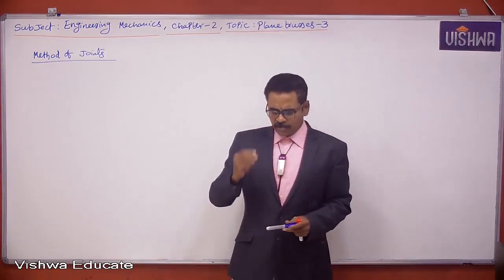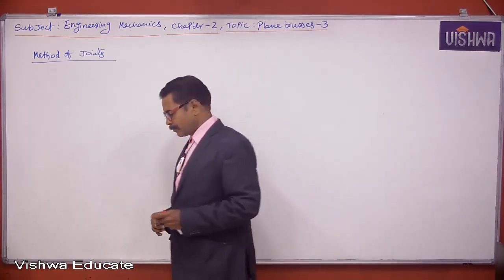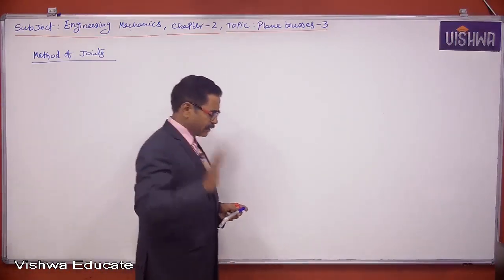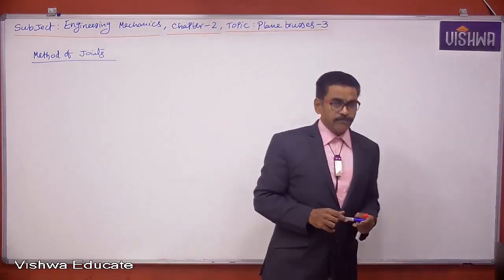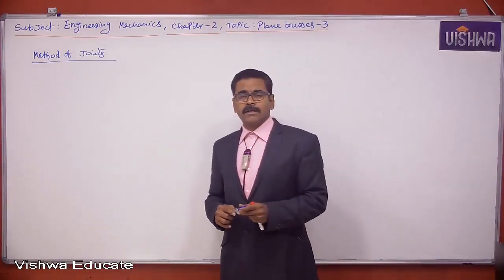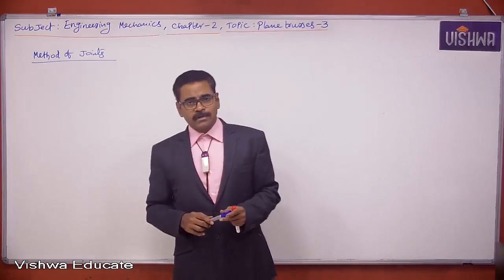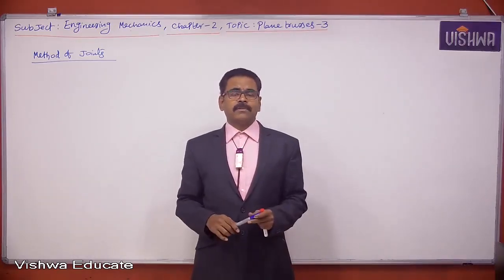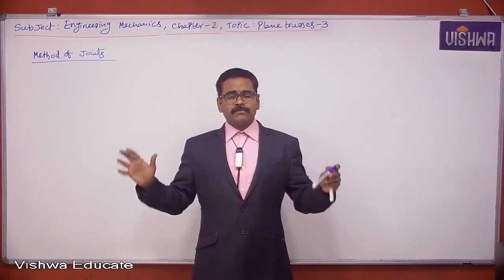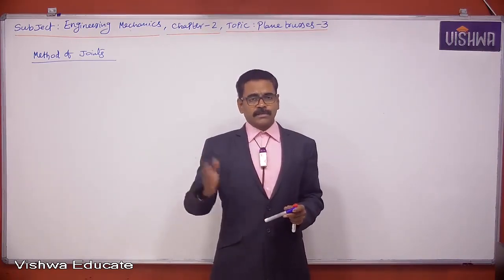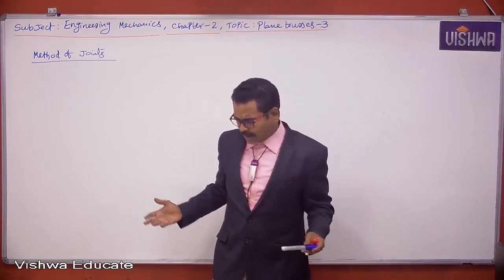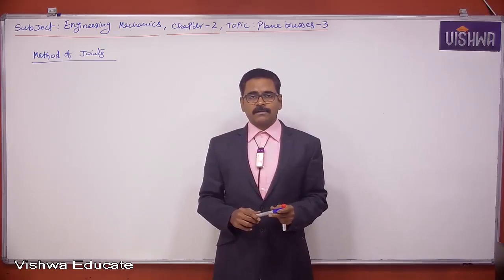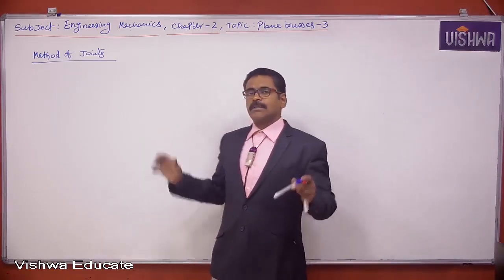Usually, third point, at the beginning, find support reactions. In most of the problems with method of joints, we find support reactions, then we proceed. Always it is not necessary, but majority of the times we need support reactions. So this is regarding method of joints.